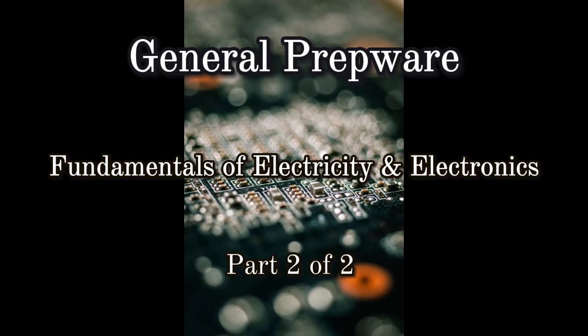How much power will a 12-volt, 1 horsepower DC electric motor that is 75% efficient require? Note: 1 horsepower equals 746 watts. Answer: 994.6 watts.